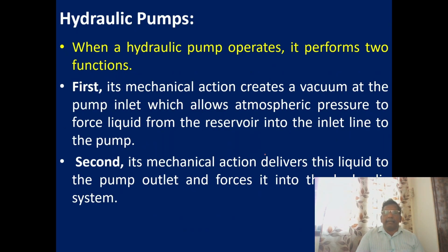A hydraulic pump performs two functions. One, it creates a vacuum. So demeshing and meshing, for example. It creates vacuum at the pump level, so volume gets increased, which allows the atmospheric pressure to push the oil from the reservoir. So it pumps the oil or liquid from the reservoir. Second, its mechanical action delivers this liquid to the pump outlet and forces it into the hydraulic system. Okay.